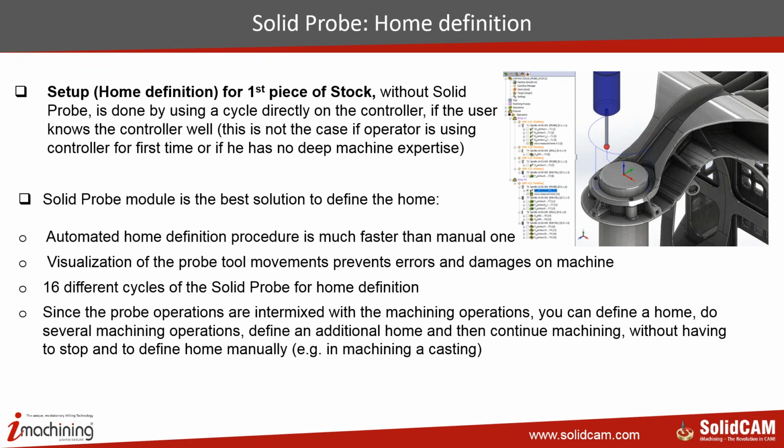In those cases, for every single part that you put on the machine, you have to check your home position. And if something is not exactly in place, you update your home position. Most people do that manually, or you have to learn all of the cycles that the machine or the probe has, which people may not know as well, and you program by hand.